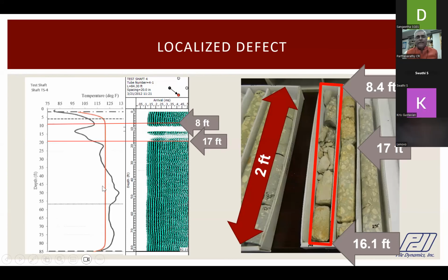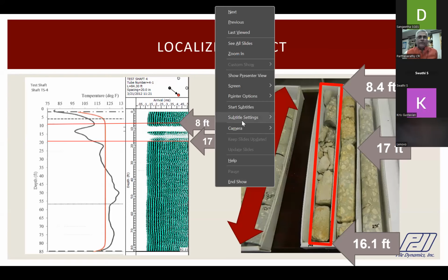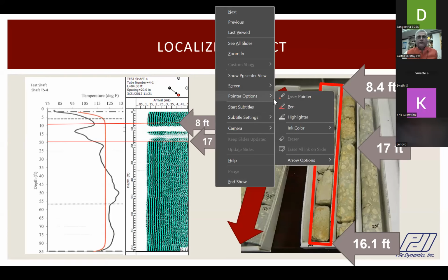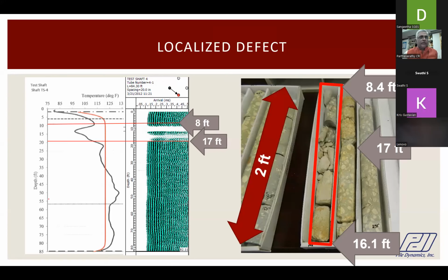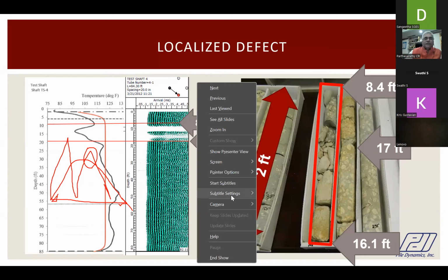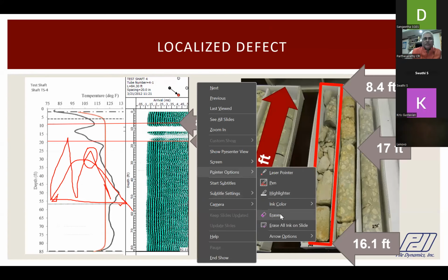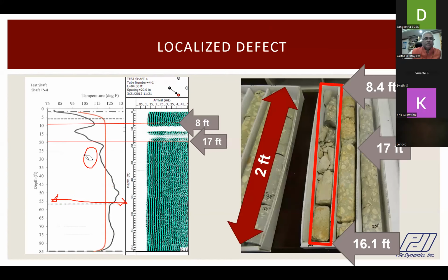But if you do a PIT test here, somebody asked me what the PIT test will look like. The PIT will always look at a larger pulse width. But if you do this testing with a small hammer, then you get a sharp peak, a lesser pulse width, and the positive signature just close to the pile top. So if you use a bigger hammer, this larger pulse will mask your defect close to the pile top. That's where the calibration of your hammers becomes extremely important.